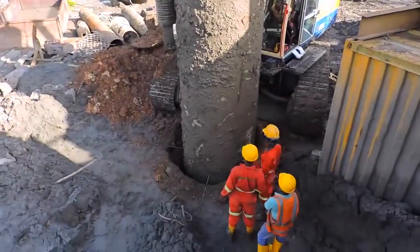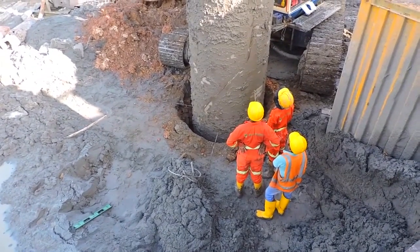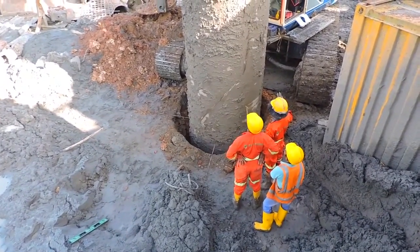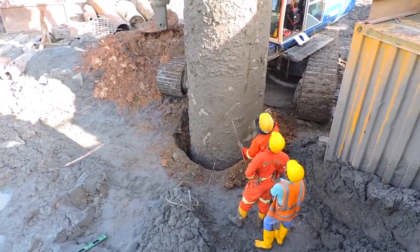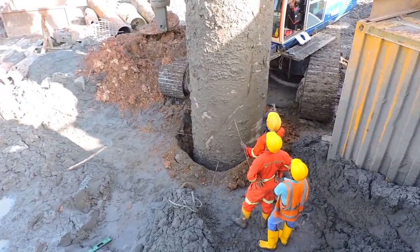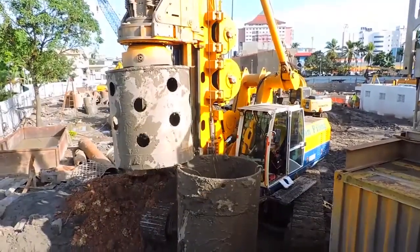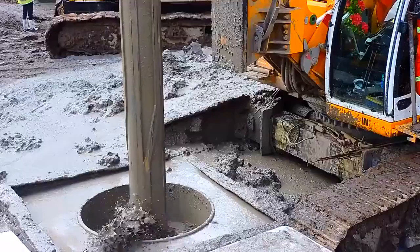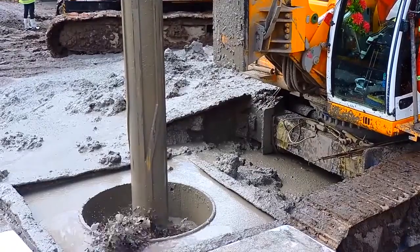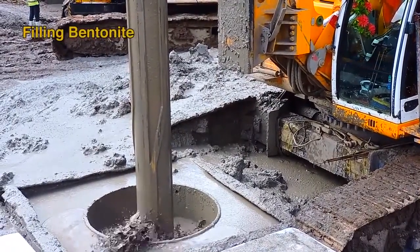The primary function of the casing is to prevent collapsing of the loose soil at the ground surface. It also guides the drilling tools. Soon after the casing is installed, the casing should be filled with the drilling fluid called bentonite. Bentonite is a special clay that can swell and gel once it is dispersed. Bentonite supports the excavation by exerting hydrostatic pressure on the walls of the drilling hole.